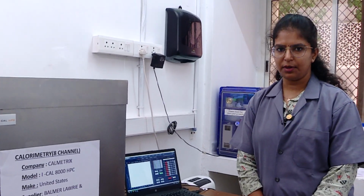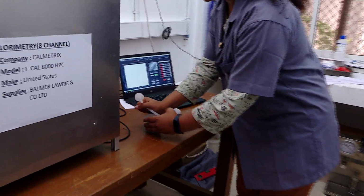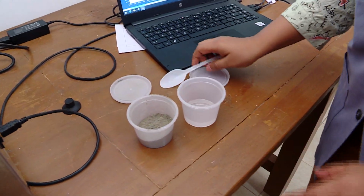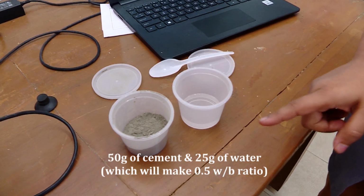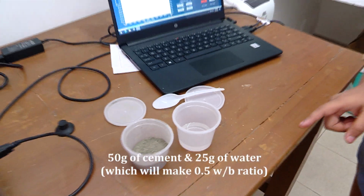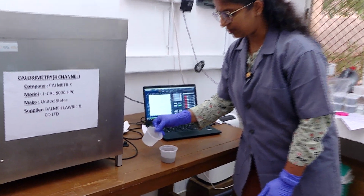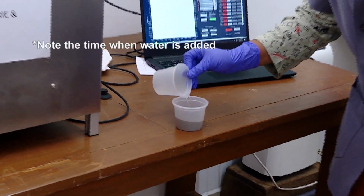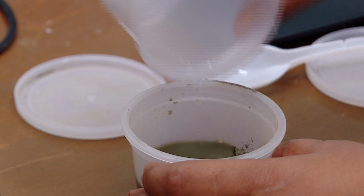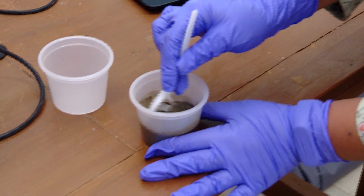Let us get into the sample preparation part. Here we have measured and kept ordinary Portland cement in the vial and distilled water. So we have measured and kept 50 grams of ordinary Portland cement and 25 grams of distilled water, which makes a 0.5 water to binder ratio. Now we will add the water to the cement, and we have to note down the time the moment we add water to the cement, and we have to properly mix to avoid any lumps. We can even opt for a handheld mixer for proper mixing.